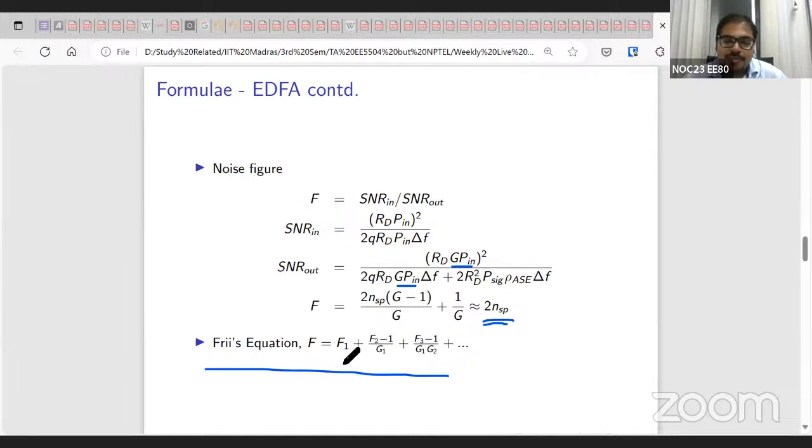That is because the noise figure of the first RF component will contribute its noise figure, but if this first stage also has large gain, then subsequent blocks will contribute low noise figures. So in an RF chain, the first stage will be a low noise amplifier. Second stage can be a mixer. Then there will be some other filters also.